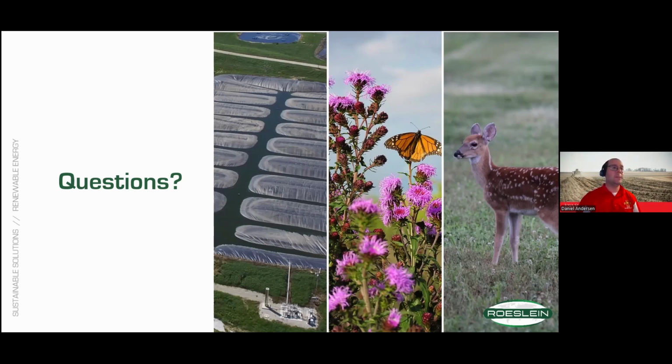That was one of the questions I was going to ask you. How do you winterize? What does a winterization of your cleaning equipment especially look like? A lot of our stuff sits outside. We don't have it inside buildings. We are knocking out water as part of the upgrading system, so anything that's condensing water, we'll have insulated and heat traced. The membranes need to be temperature controlled, so they're usually in a container that has a heater in it. And there are certain parts of the process that we're insulating to maintain heat that we've created from, let's say, waste heat from the compressor.